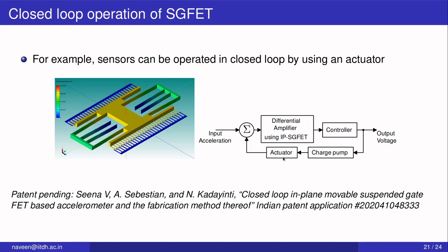So this actuator, mind you, is again a micro electromechanical system. So it has electrostatic forces and mechanical forces which will determine what is its actual operation. So the same procedure we have used for the transistor can be used for the actuator. Essentially you can construct a lookup table for the actual position of the actuator for different actuation voltages. Use that as a lookup table to close this loop and do an entire loop simulation.